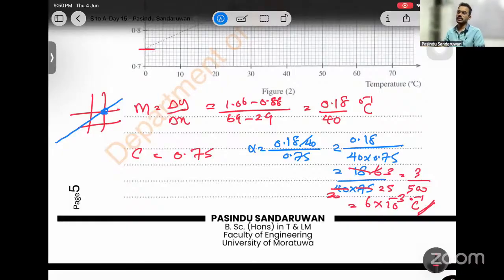Fine. A small calculation. And be very careful when you are selecting 2 points, because always it should be 2 further points with exact intersections, and they should not be the points given. If you have more than one possible pair, the best option is going with the furthest pair, because that is the pair with minimum percentage error. Higher the distance, lesser the percentage error. All right.